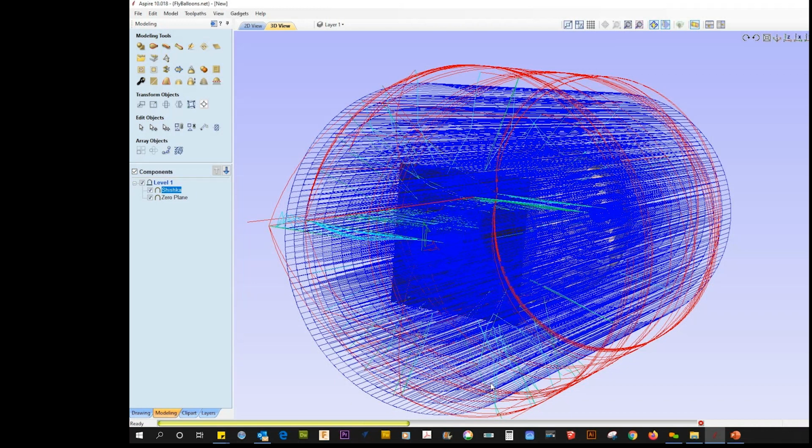So when the rotary turns 180, the Z raises and then it comes back down. I haven't seen anything where they have corrected that. So I don't use the offset in Aspire because of that.